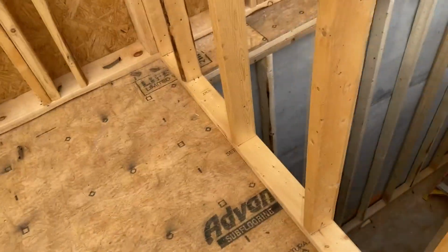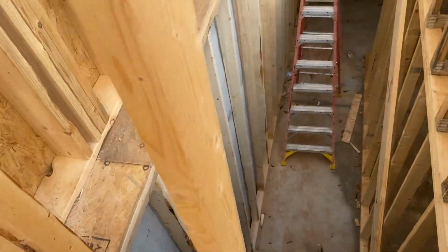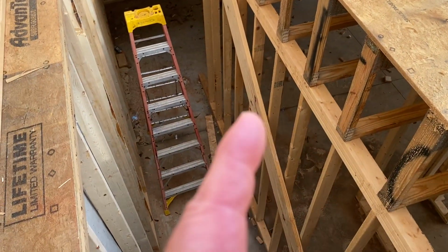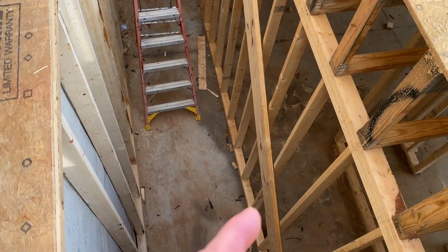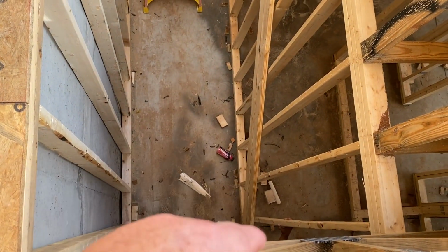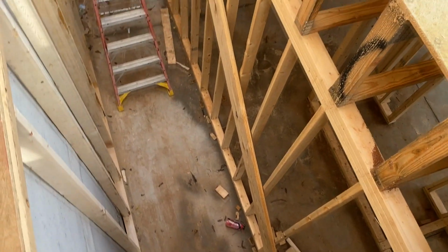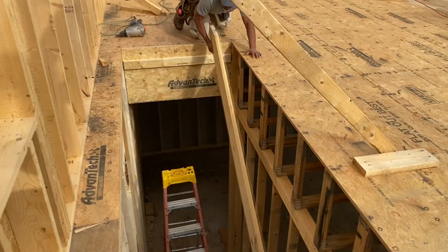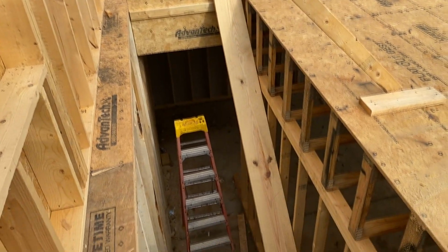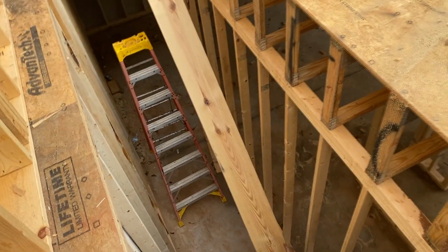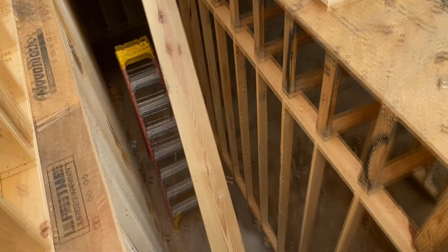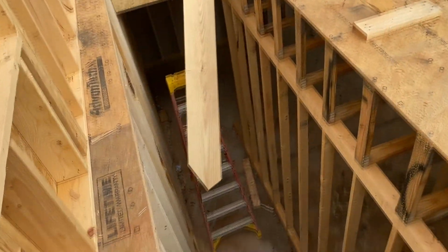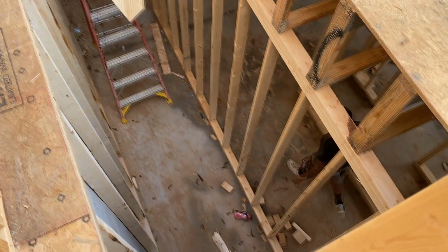What we're looking for is to check our headroom. Before we cut all of our stringers out, we measure down to the line on the one that's close to this headroom to make sure we got our 6'8", and we're going to have about 6'10". Now we can cut out our risers and treads. Now that we've verified that, you don't want to get that whole thing cut and then come to find out it's wrong.